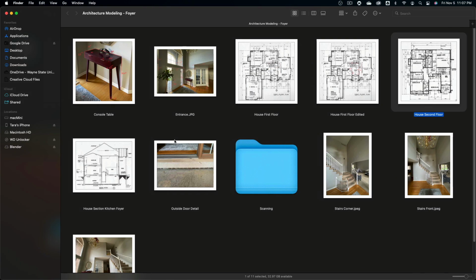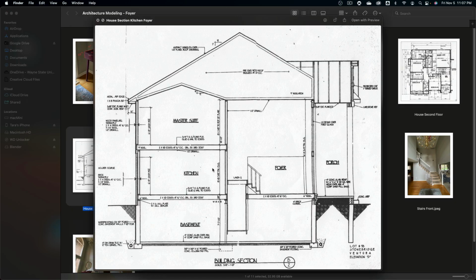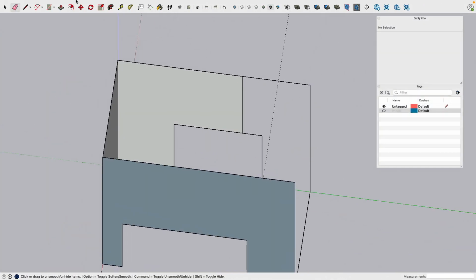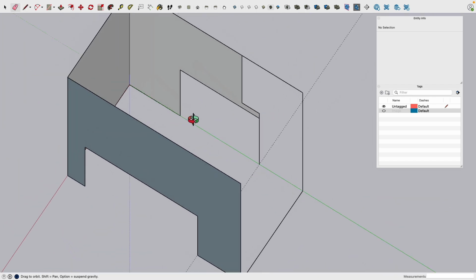Okay. We go back. What we now figured out was actually this line, but currently I drew this till here. There's also the thickness. If we go to the section view, this is at least 10 inches plus subfloor. Let's keep this at 10 inches for simplicity reasons. Okay, so pen tool, there we are. Let's go up along the Z axis, 10 inches, bring this over. Zack, there we are. Very nice. Cool.